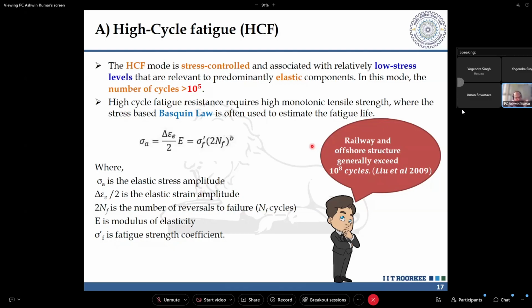Specifically, it depends upon whether your steel is a ferrous alloy, or if you look at aluminium, it might have a different kind of behaviour. So don't stereotype fatigue into, oh no, you said it wrong, it is greater than 10^4 or 10^5. He is also right, and the person who is saying 10^6 is also right. It depends upon what metal you are looking at and where it is getting applied, right?